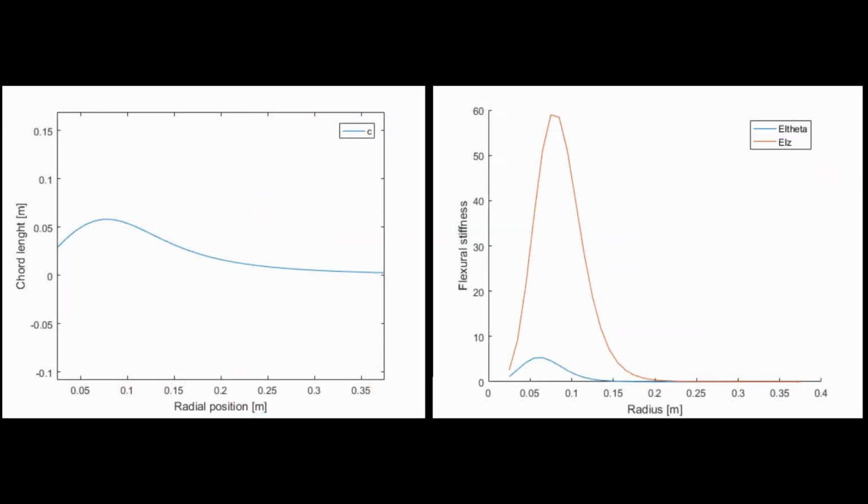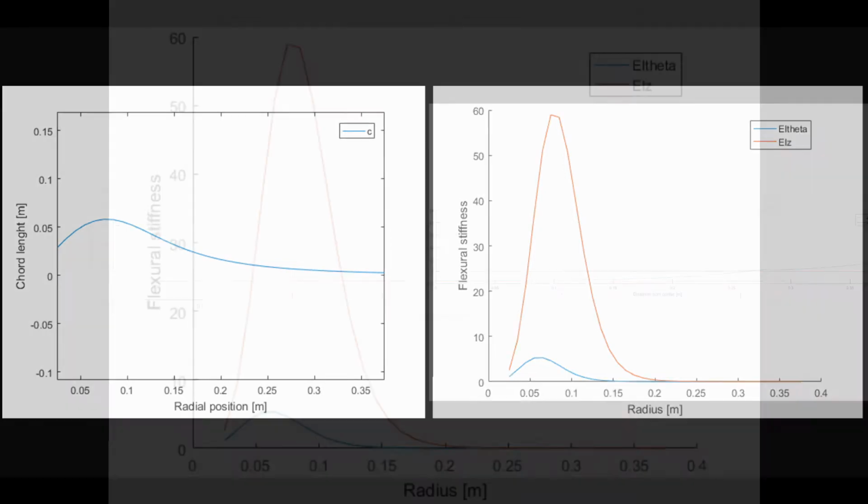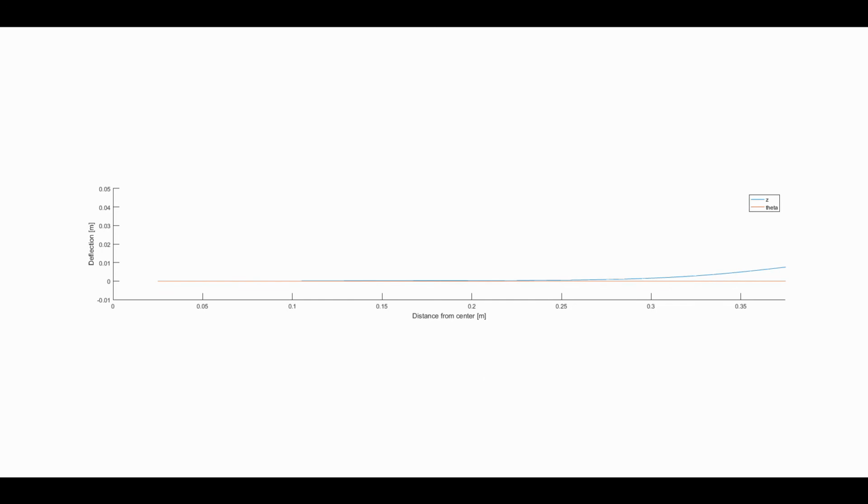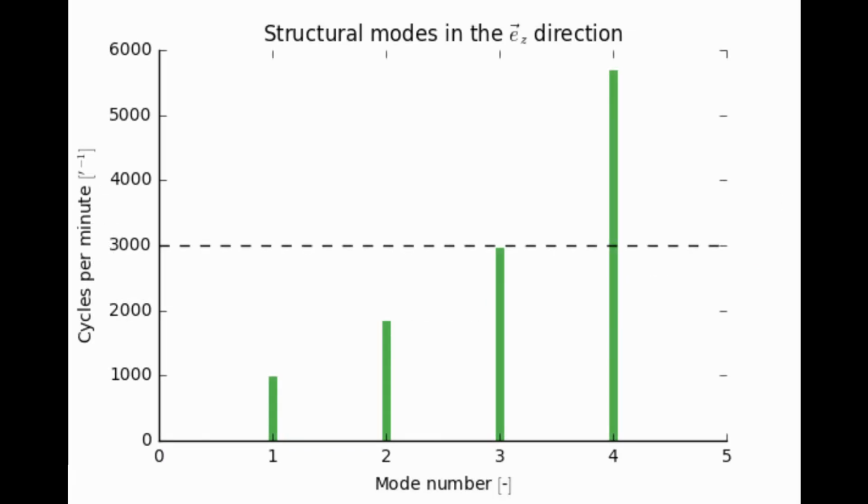The aerodynamic calculations are done by interpolating lift and drag polars and using a rotating solid disk method for the speed distribution along the blade. The deformations were computed using a first-order implementation of simple beam theory. A centrifugal force correction was then applied as a form of negative buckling load. Finally, the deflected shape, resonant modes, and maximum stress checks were obtained.